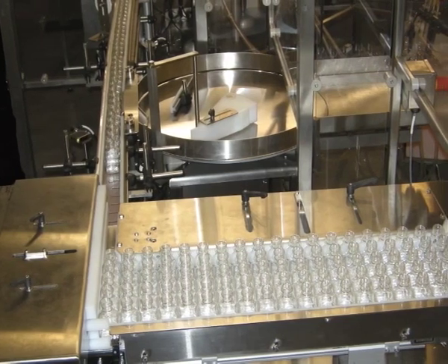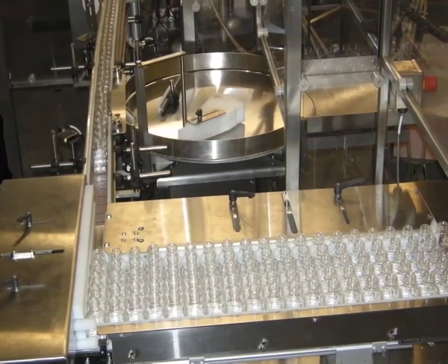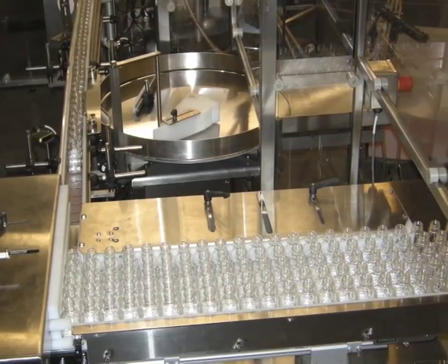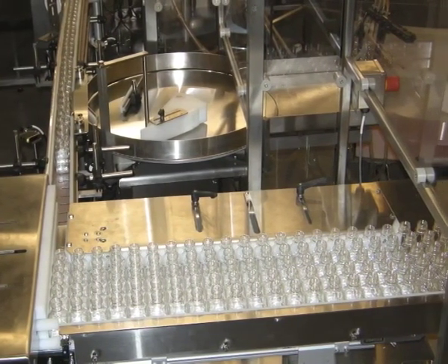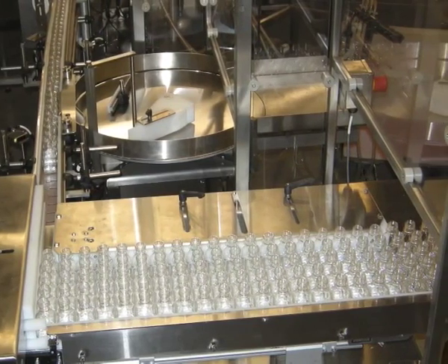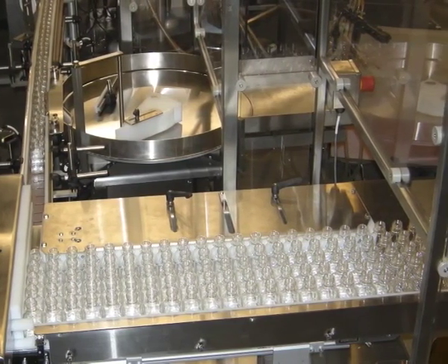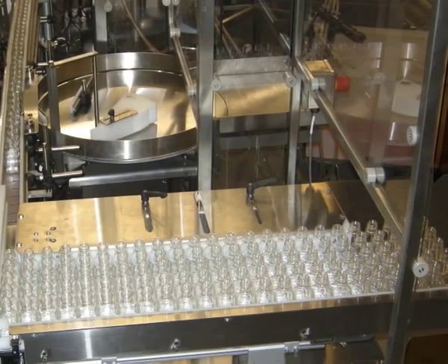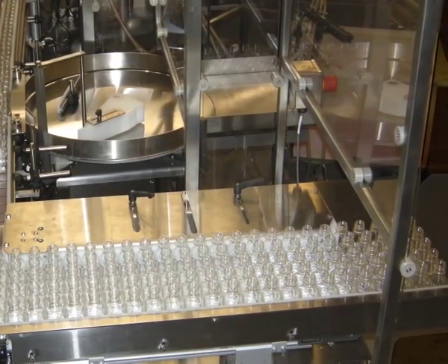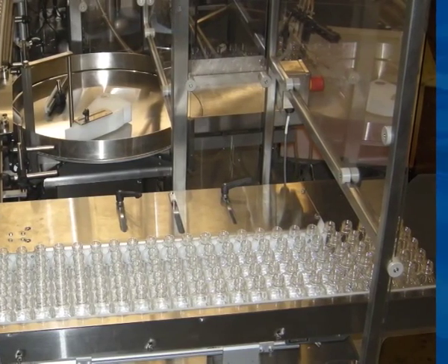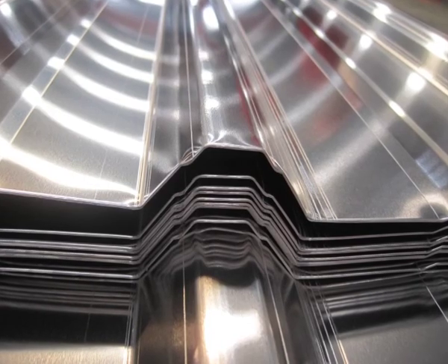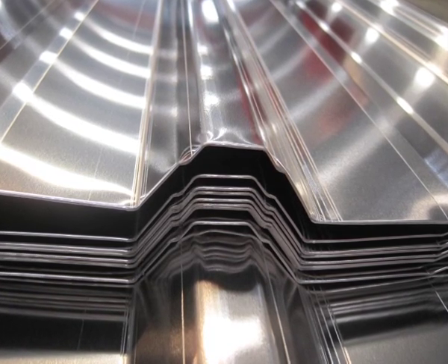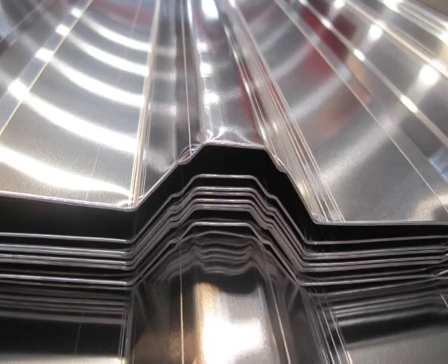Aluminum aerosols are inherently more expensive than tin plate but can be made in one piece with neither side seam nor bottom chimney. However, for practical or economic reasons, these monobloc containers are usually restricted to the smaller sizes of aerosols. Larger sizes are produced in two pieces, that is, with a continuous side wall and a seamed on base.